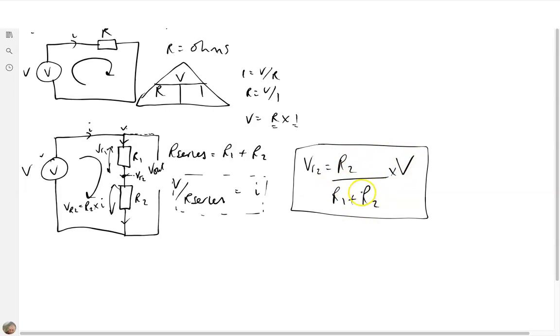Now it doesn't matter whether we replace one of these resistors with, say, an inductor or a capacitor. We just have to replace the associated resistor with an impedance, as it's called. So an imaginary impedance, and this is something that we'll look at as we move forward. And this is how we build filters that attenuate voltage levels as frequencies change.